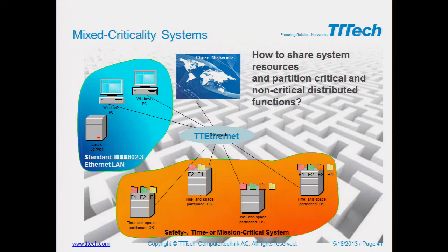So there are two approaches to take care of this asynchronous information, which is sporadic and is not so important. One was given by a protocol that became very fashionable in the past 5, 6 years in cars. It's called FlexRay. FlexRay combines these two kinds of mechanisms, but in a very constrained way.